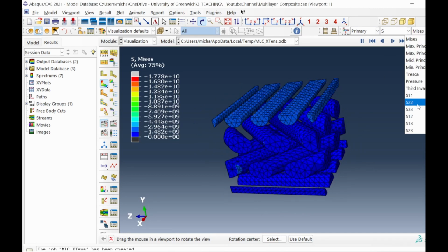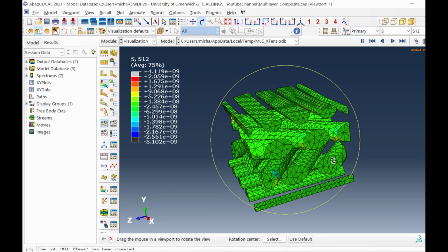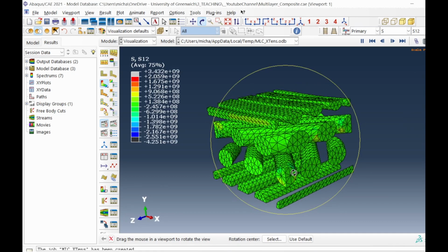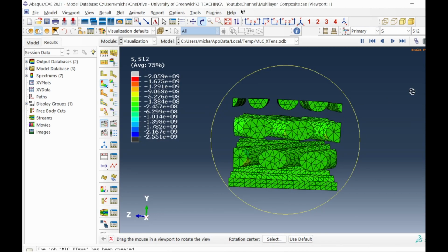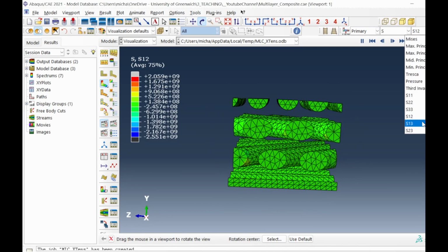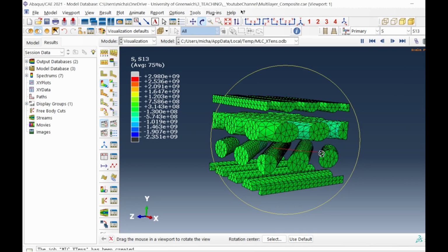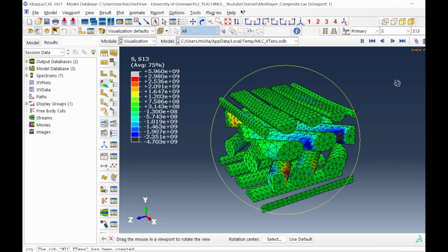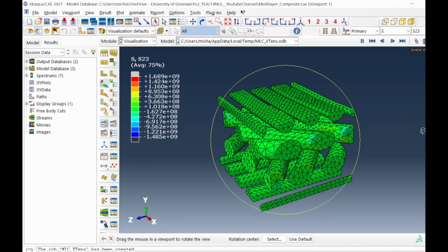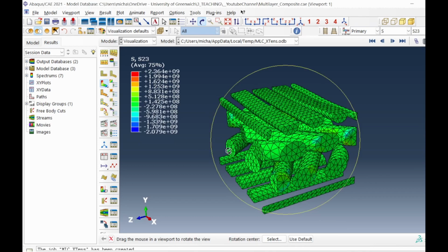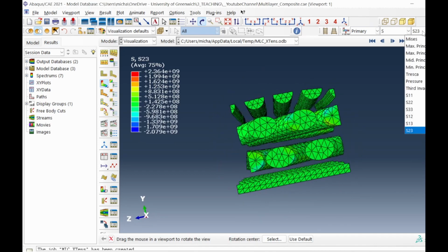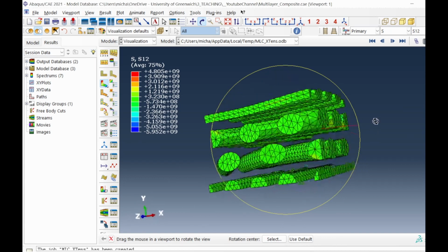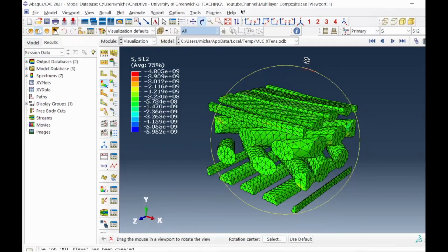So if we look at the shear deformation, you can see the predominance of shear in the plus or minus 45 degrees as they keep rotating. So we can look at all possible angles, possible shear deformation, which is what we expect. So they would take a lot of shear deformation as the body continues to rotate under the uniaxial load that is applied onto them. Okay, so this is sort of what we'll see here.